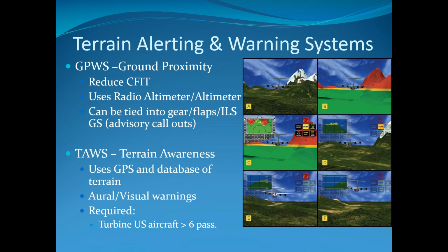They also, it's that same system that, in that video I had, you can hear the thing calling out the altitude levels, where it says 50, 40, 30, that all comes from this system. It's calculating your altitude and it's telling you where you're at. But it's used for a lot of different things. The same system is used for the wind shear alerts, for the microburst detection stuff, for